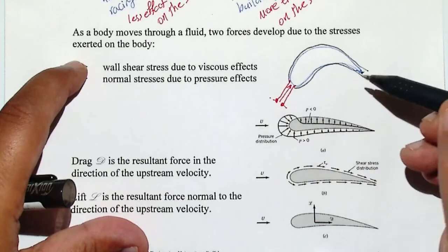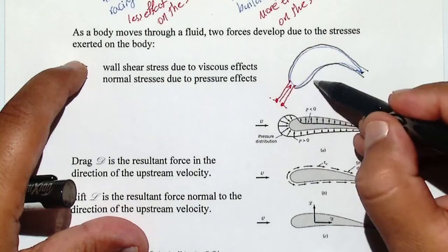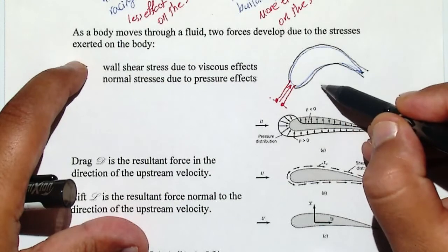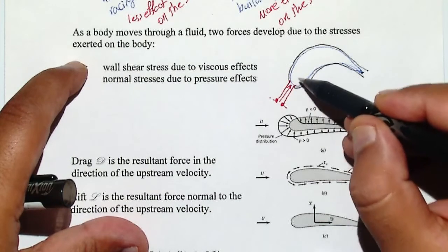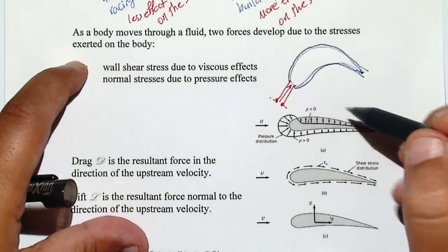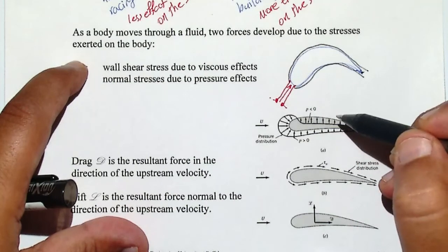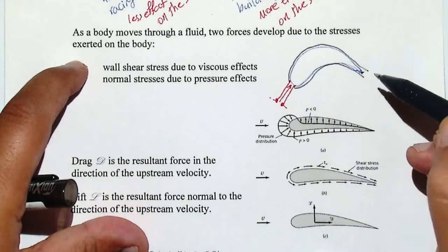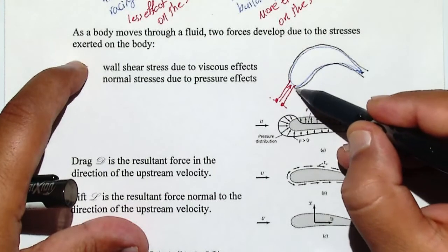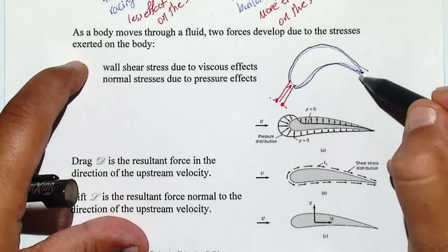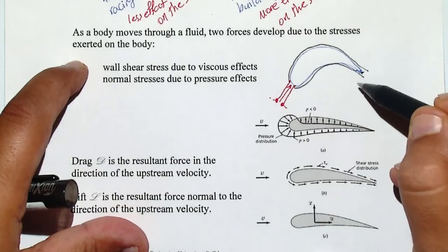And since it's irrotational, these two are two streamlines, but you can say that the constant in Bernoulli's is the same. We talk about that in chapter 3, that Bernoulli's could be applied only on one streamline, but if it's irrotational, you can assume that the constant for element 1 between 2 points on one streamline could be the same for all the streamlines as long as the flow is irrotational.